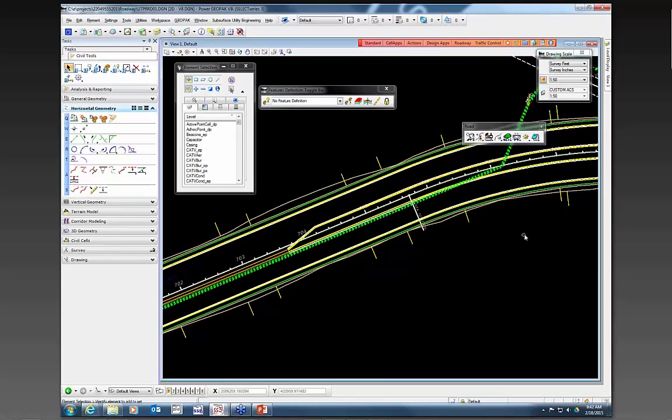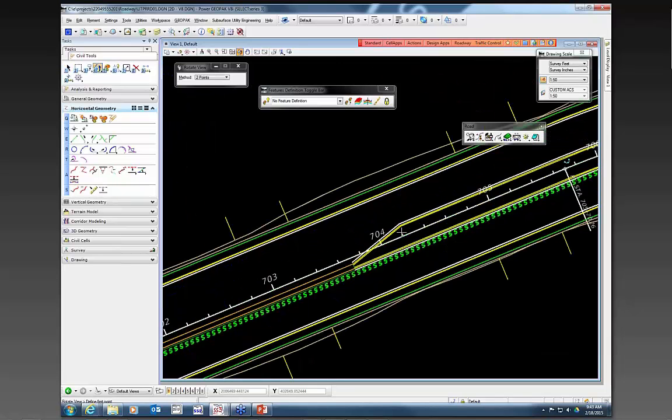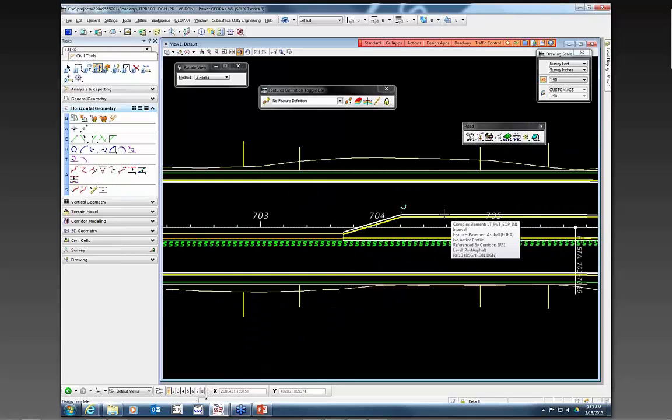And basically you would do this for any type of proposed or existing utility that you need to change. And also, as a reminder, all utility lines have to be labeled. The existing utilities should be labeled with a disposition such as to be removed or to be relocated. If not, they're assumed to remain. And then also, all overhead electric utilities must include the voltage in the label. And you can find out all this information in the PPM, what the labels should say, and what should all be included.